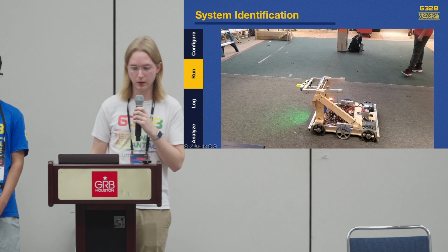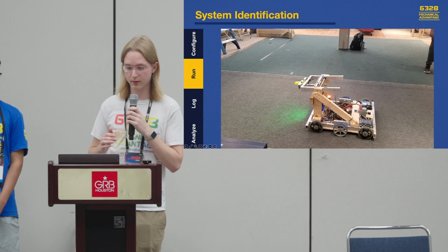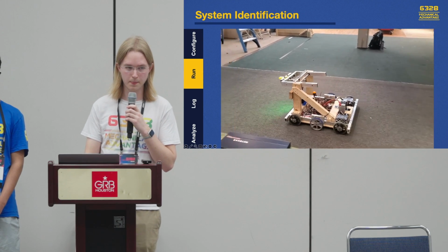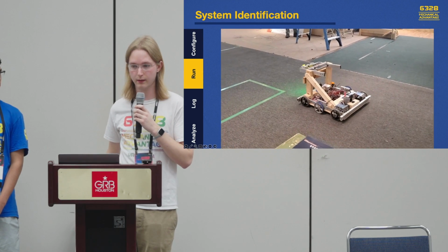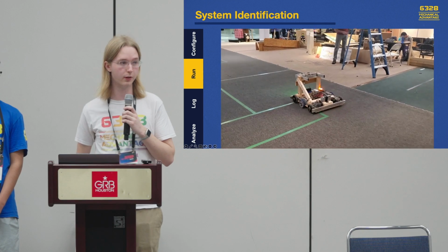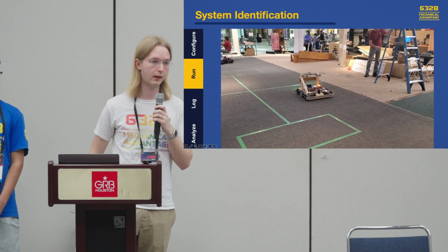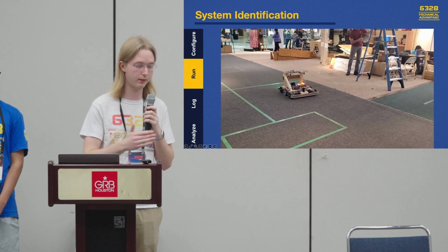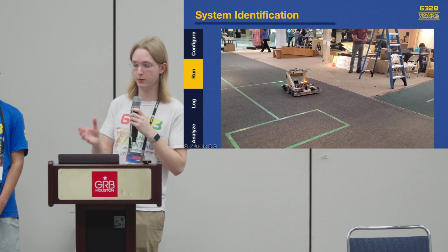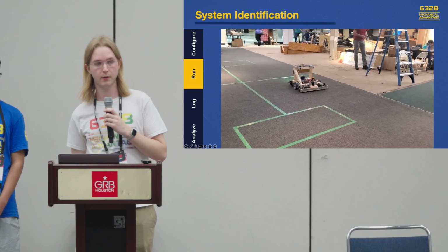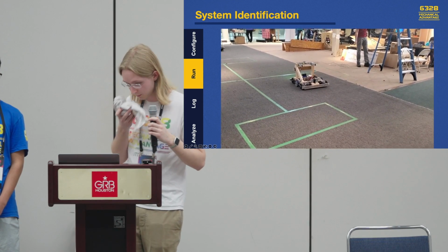Okay, so now we're going to run our 4 tests in auto. Here's a simple example with a differential drive. So first we're doing our quasi-static tests. This is where the voltage slowly ramps up, and we're looking at how that affects the velocity as it increases. So the relationship between voltage and velocity. In a moment, we're going to run it in reverse as well.